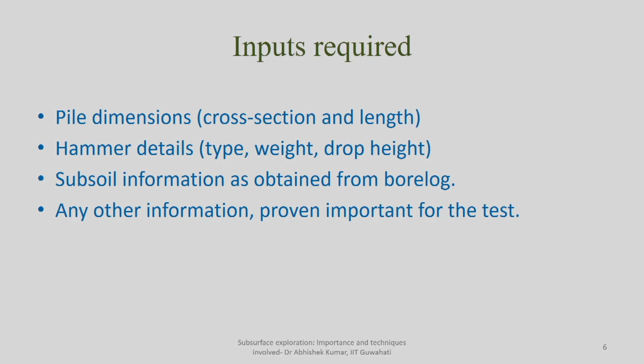Subsoil information: depending upon the subsoil information, whether the pile has to be designed as a skin friction pile or end bearing pile, or a combination of those, will come into existence. Generally this subsoil information you will get from bore log data. Then any other information, to give you an example like hammer impact efficiency, or if problematic soil is there, some collapsible soil is there, water table depth, other things which can actually affect your field recording can also be taken into account as possible input for analysis.